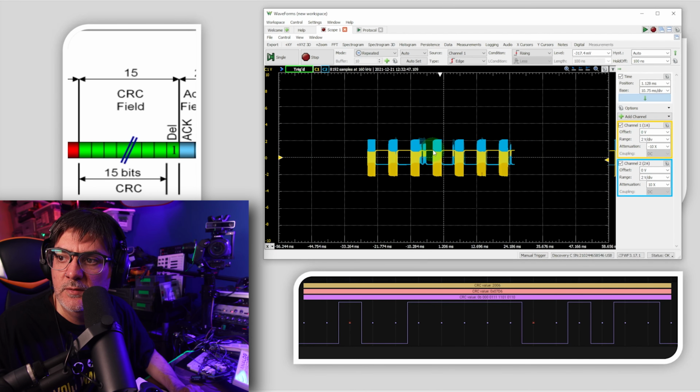In this case, I'm filtering everything on the wheel. These are the 3 streams of information. This is the ID, pretty much, because there is no movement here at all. When the CRC doesn't change, it means that it's the same information all the time. And that's how you decode basically each one of the packages on CAN. And the CRC information is going to do the checksum. If you want to do it by yourself, that's the information.